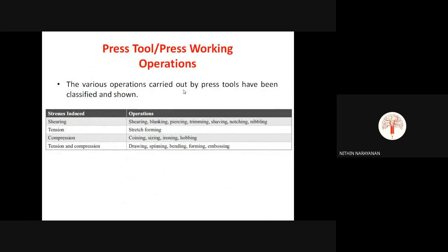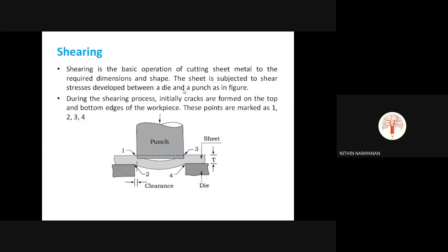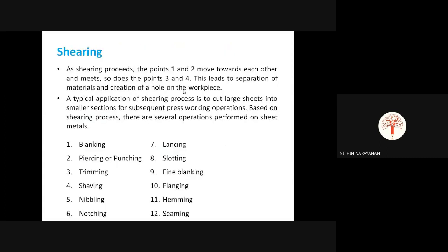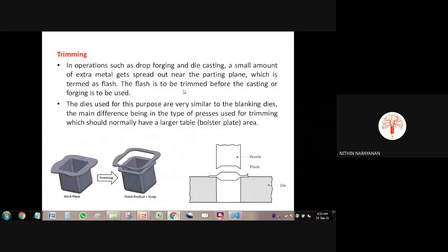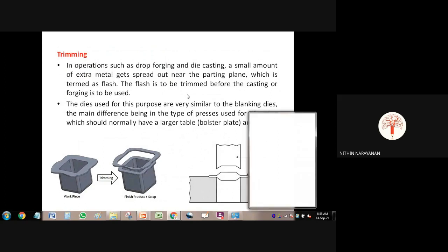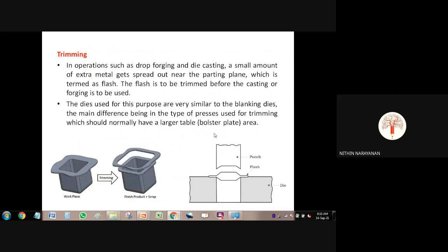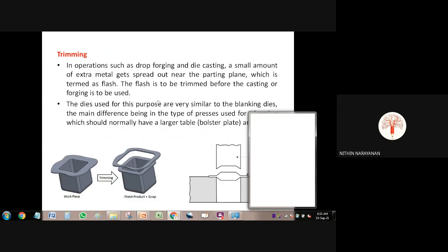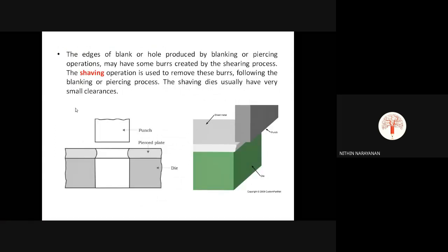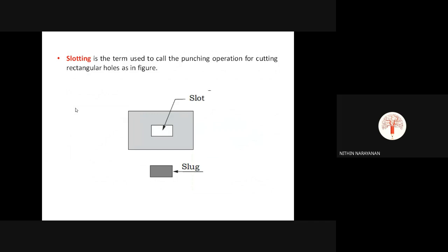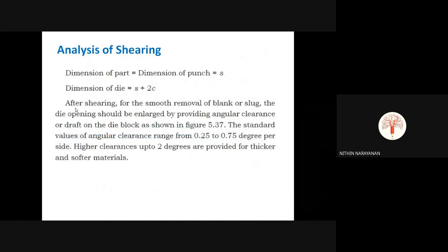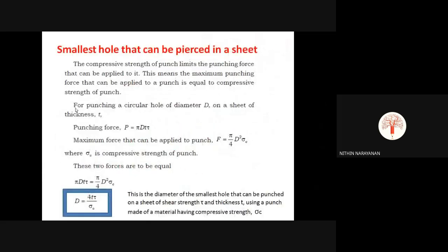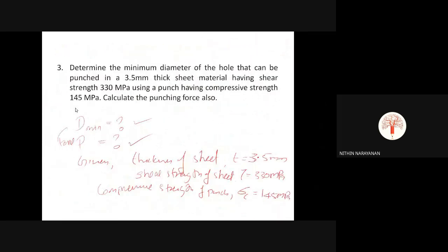First we looked at shearing operations like blanking, piercing, trimming, shaving, notching, nibbling and so on. Then we did analysis of shearing, found the shearing and punching force, and looked at two or three problems.